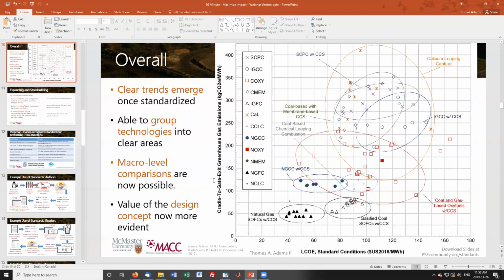Okay, so SOFCs have been around for a century. They're not new in the sense that the space shuttle has used them. Google and Amazon currently use them. So right now they're a niche technology. They're primarily used because they are low noise, low vibration. For example, they have a military use in drones because they're silent, especially underwater drones. And they have a use in server farms because they have low vibrations, so you don't have to worry about the read heads on your hard drives being knocked around. And you can put these server farms in some isolated cold place for heat management and then power them locally with SOFCs. There's a couple of companies that are building them for those purposes primarily.